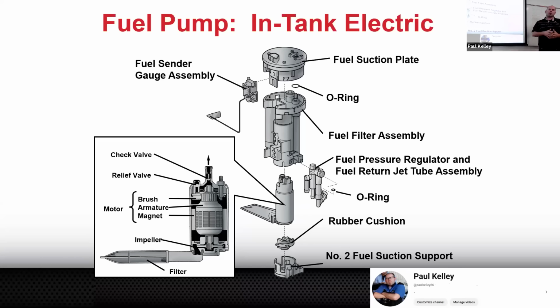So when he said, what do I do? I was kind of like, you know what it really needs? Diagnosis. Because I don't know. But if I was a gambling fella, I bet you this is what's bad. These fail a lot. However, sometimes the actual gauge fails. And of course, he lives near me, so there's mice chewing on wires. So I'm not comfortable enough to say, oh yeah, it needs that fuel level sensor, because I didn't make any measurements. I didn't do any tests. I really actually don't know.